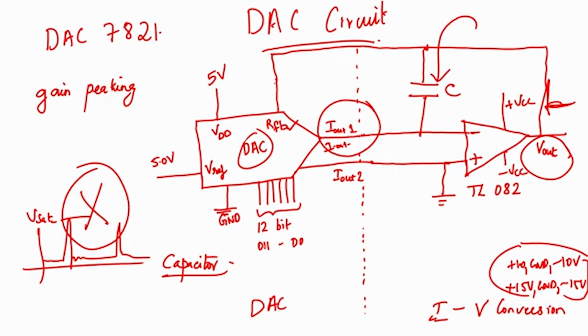Okay. So, this is how with this capacitor we will get smooth output signals, but we pay a price for this. I will not get into details again, but if you do circuit analysis of the output voltage, because of this capacitor you will find that the output gain gets reduced a bit, and we might not get the full voltage fluctuations at the output, but nonetheless we will be able to see changes in output voltage as and when bit sequences are changed, which is digital to analog conversion, correct.